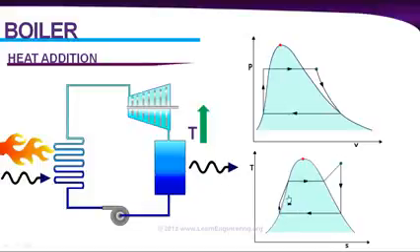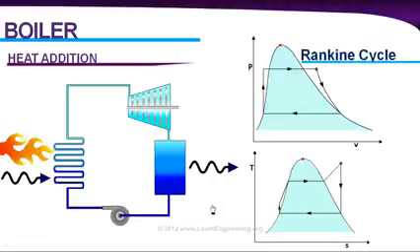So obviously temperature of the fluid will increase back to its original state, and you can see it over here. Temperature rises from here to its original state. And during this process, pressure remains same because fluid is free to expand. Now the cycle is complete, and this cycle is known as Rankine cycle. And this is a basic Rankine cycle. In order to execute this Rankine cycle in a power plant, you will need some other accessories, especially for heat removal and heat addition. We will see that.